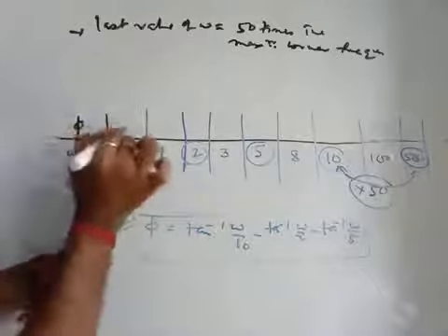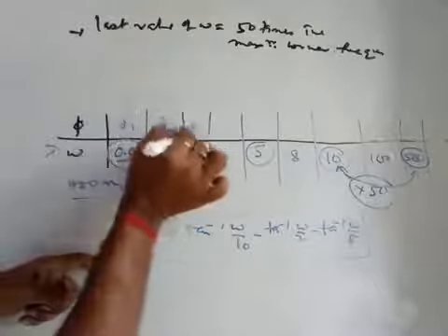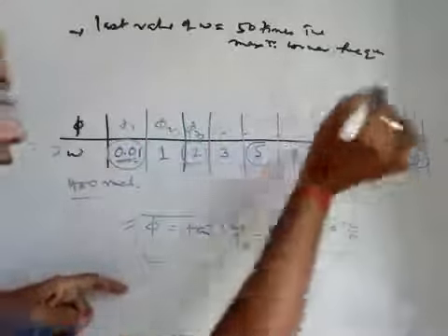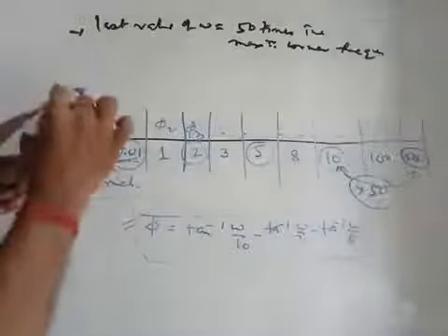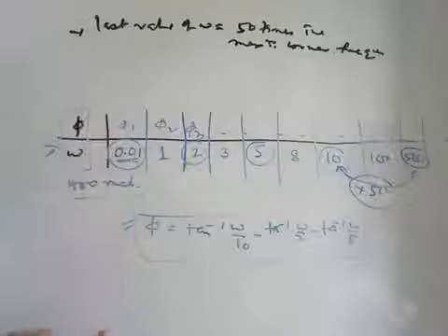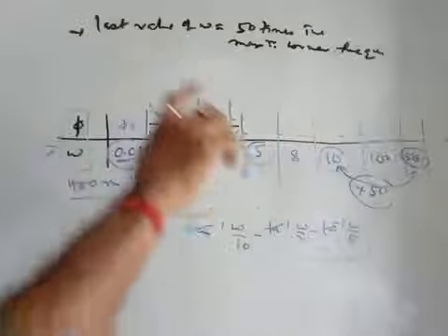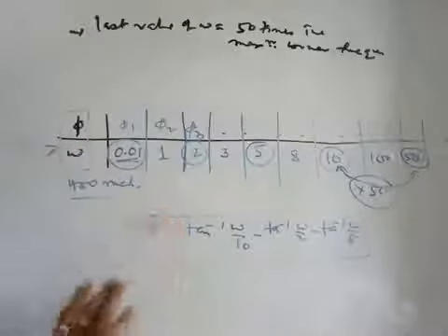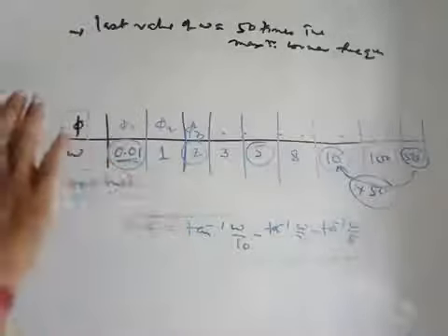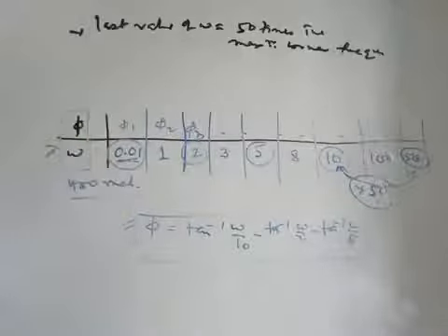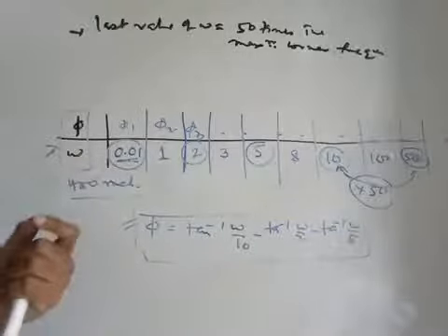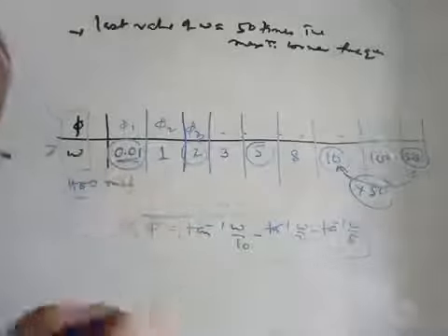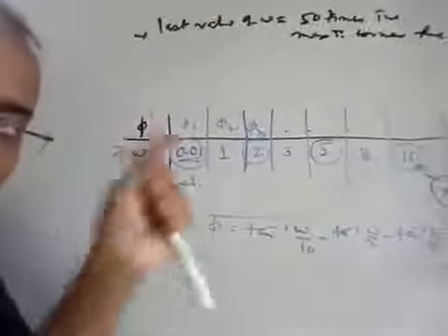So this is your phi 1, this is your phi 2, this is your phi 3, and all these values. You just get phi versus omega, and all these values you have considered. Then, once you get these values completed, you have to scale the semilog graph paper in the lower, that is the bottom part of this graph, where I have already shown you that the angles, that is the phases, normally start from 0 degree toward downward.